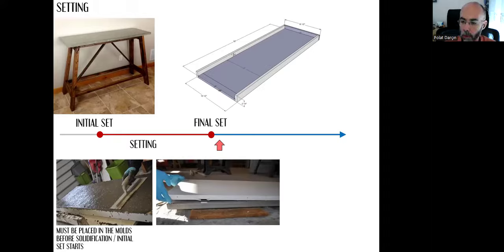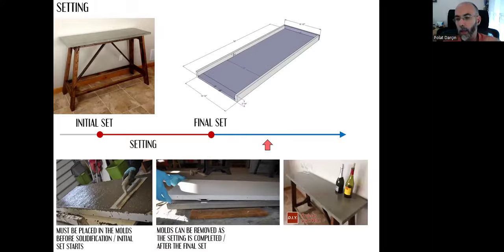We can remove the molds because it's solid enough to hold its form, but we shouldn't apply any loads. We need to wait a little bit more so that, with the loads applied, it's hard enough to carry and transfer all these loads.